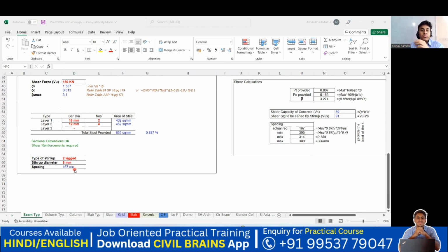So 167 is not a round figure. Okay. So what we can do, we can lower it down. Always the spacing, whatever you are getting, lesser than that we need to provide. We cannot increase the spacing. If you're increasing the spacing, the number of stirrups will come down. If the number of stirrups is going to come down, the Ast is going to come down. So in that case, it will not take care of that load. So now what I can say, I can go with this.